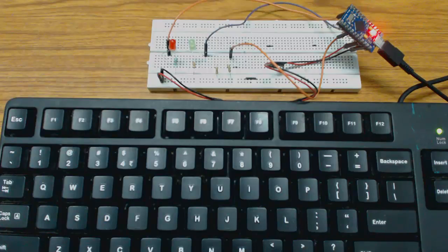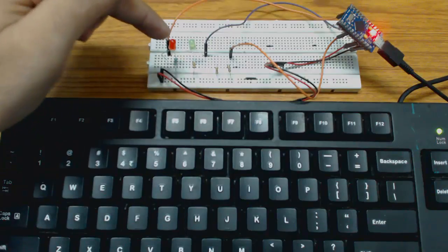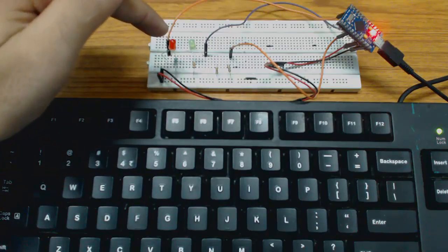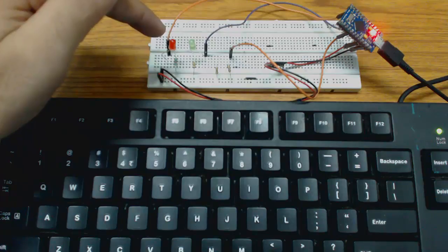This is the demonstration video for the ioport controlled USB application. In this application, we can read, write or set the data direction of an input-output port of ATmega32U4. At the device end, we have one LED connected at PB4, pin number 5th of the port B,